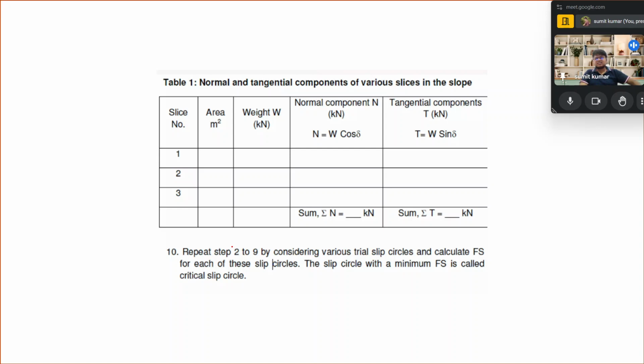Now, how do you create a solution? Over here, the symbolic table is also represented. First of all, we divide into slices. The slice number should be 5 or more, at least 5. So the slice number is mentioned over here. After that, you have known the width as you have decided the number of slices, or maybe divide into equal width, which is a common assumption. So you know the width, you calculate the height at the center,